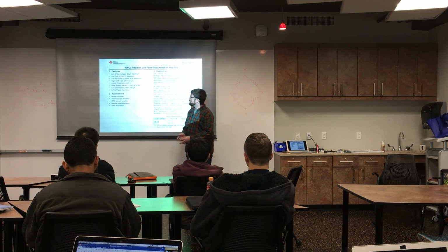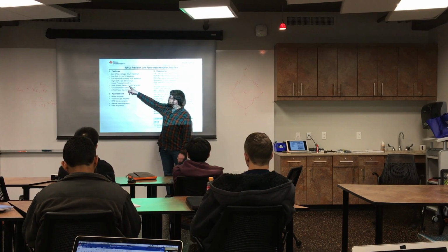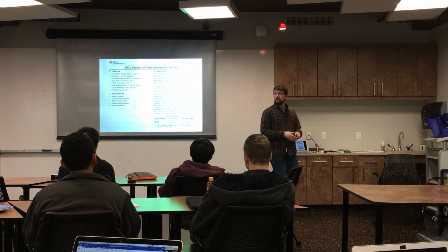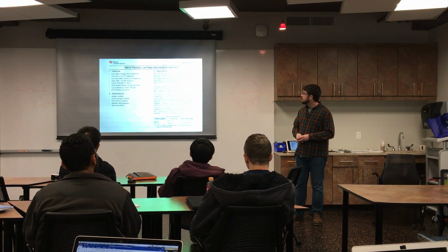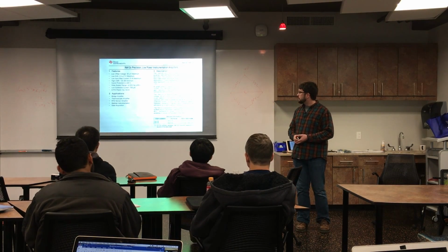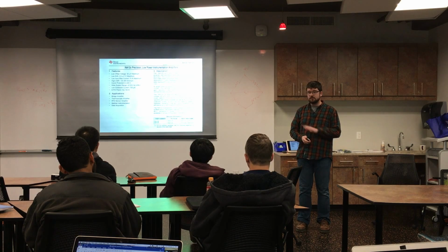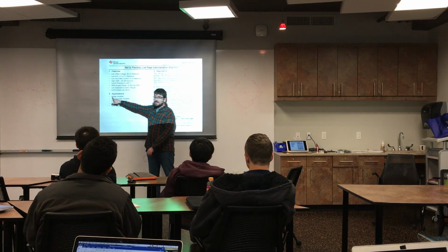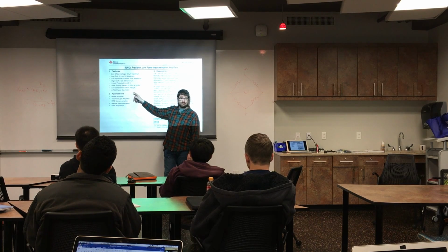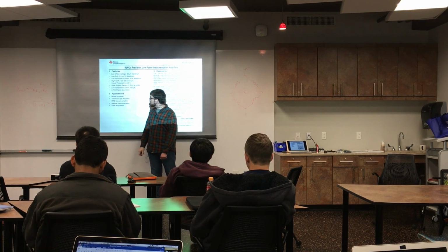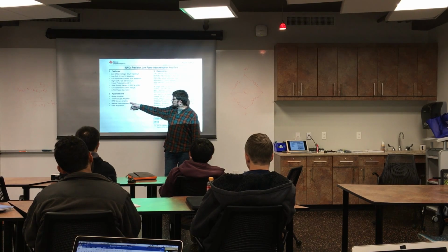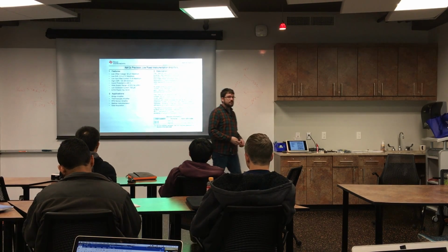Really, like the INA105, it had a pretty wide supply voltage range. These can run from plus or minus 2.25 to plus or minus 18. Things are really starting to push down lower and lower voltage these days. And so 700 microamp current. So these are really nice. And you'll notice under the applications, a bridge amplifier is the first one. This is purpose designed for doing things like Wheatstone bridges, scales, there's a thermocouple, RTDs, all these things that we've talked about so far.